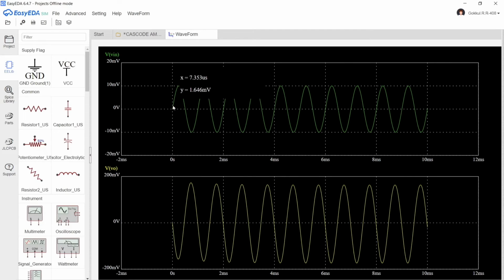And here we have 180 degree phase shift in which Vin is positive and V0 is negative. Because we have placed common emitter in input side, the input signal will be 180 degree phase shifted and the output signal will be given as input for common base and it will not make any 180 degree phase shift change. So we got the 180 degree phase shift in graph.